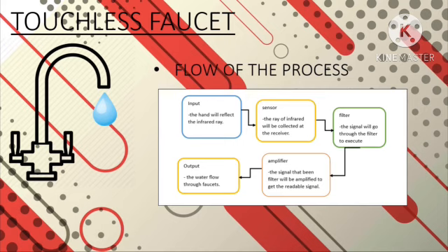Because the arrangement is non-inverting, the output signal will be in phase with the input signal, preventing phase shift caused by the amplification process. The intended behavior of the band pass filter RC circuit is to attenuate frequencies outside of a certain range while permitting a certain range of frequencies to pass through.